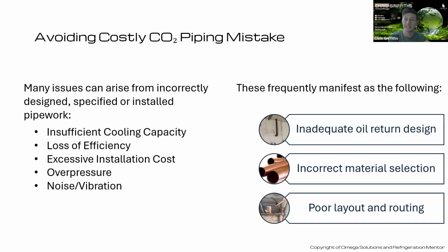But even then, we're now getting systems which operate at 90 bar out of the intermediate side through to a liquid. So we're now having to install extra high pressure K65 pipework rated to 120 bar to accommodate those liquid lines. And it just keeps going up and up and up. Also, depending where you are in the world, you may have to use stainless steel as mandated by local codes rather than it just being good engineering practice.